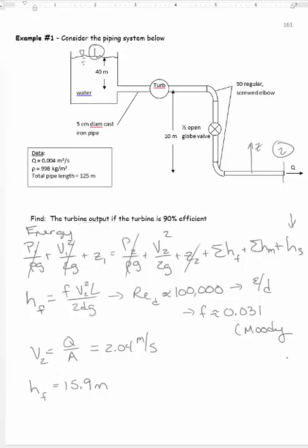Okay, so our HMs are going to be based on all of the fittings, entrance, exits, valves, whatever. You don't count the turbine as having one. That all goes into the HS. All right, so if we look at this, what I usually do is label all of my different fittings. Look carefully at this. An easy one to forget is the entrance. We have an entrance here. So that's going to be A. Here's B. It's going to be my next fitting. It's a screwed elbow. C is a valve here. D is another elbow. And then you got to look at the exit sometimes.